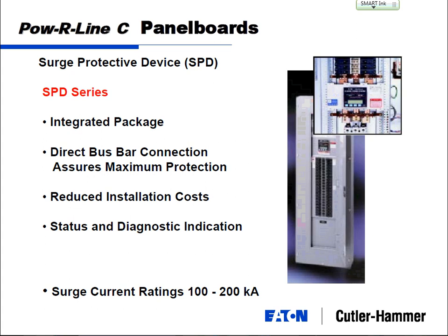The other kind is internally generated transient voltages, like a Xerox machine or fax machines. The way they work just sends a lot of transient voltages. They're going to go from that machine, funnel back to this panel board, go up the copper cables all the way to the main switchboard, and then funnel out to all the other equipment in this building until you find something that's protected by a surge protective device.